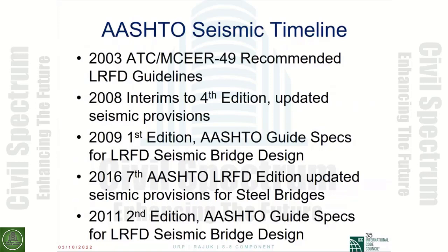So as you see here, the latest is the AASHTO LRFD, and that is force-based. And the AASHTO guide specs are displacement-based. So you have two design methods: you have a force-based and you have a displacement-based. You may want to ask yourself, which one is the best to use?